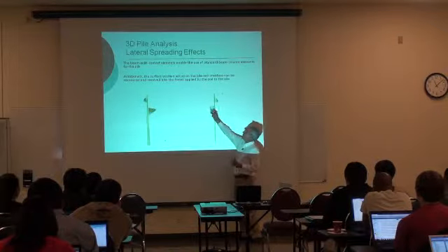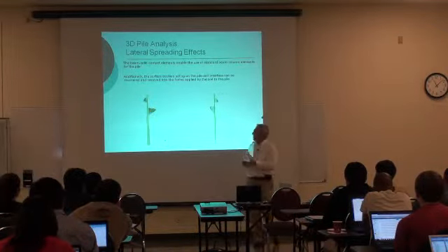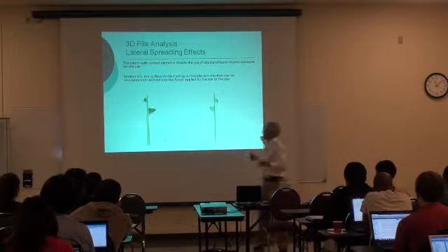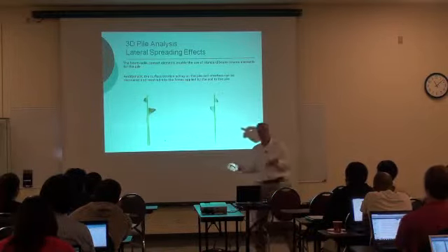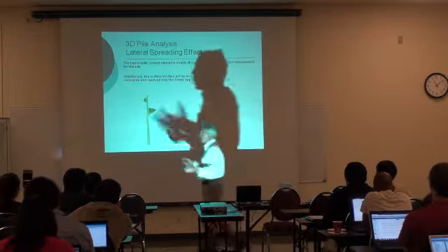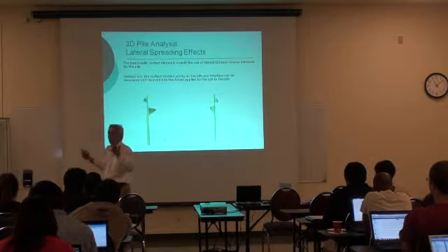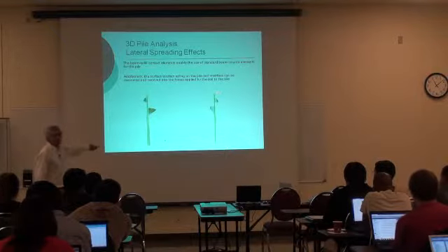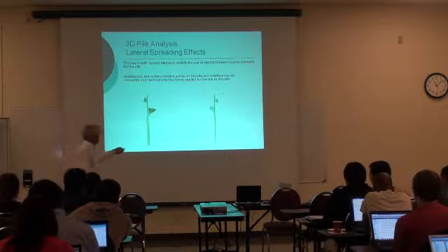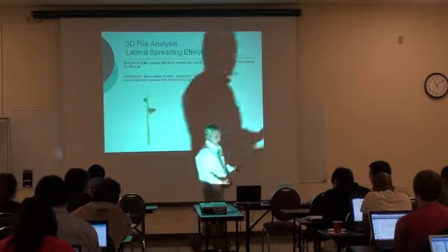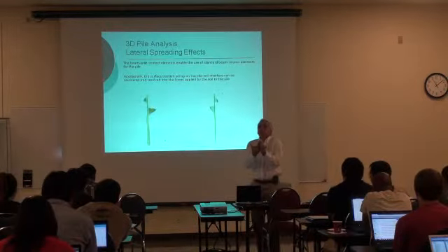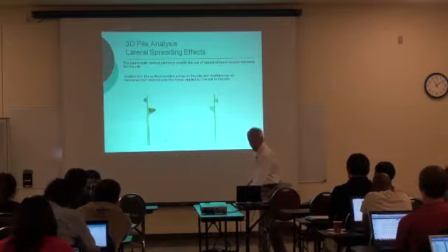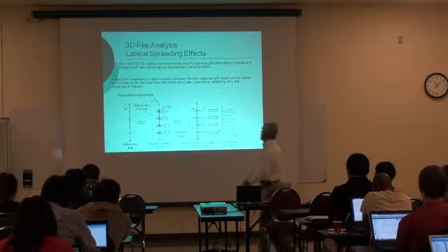Oh, this is useful because now I can start getting numerical experiments that allow me to get PY curves. All these PY curves that are commonly used in practice have been developed from experiments where the piles were pushed at the surface here. So this allows me to do the same experiments, or experiments that you cannot perform in practice in the field experimentally. So I can do numerical experiments that may allow me to get some other stuff.